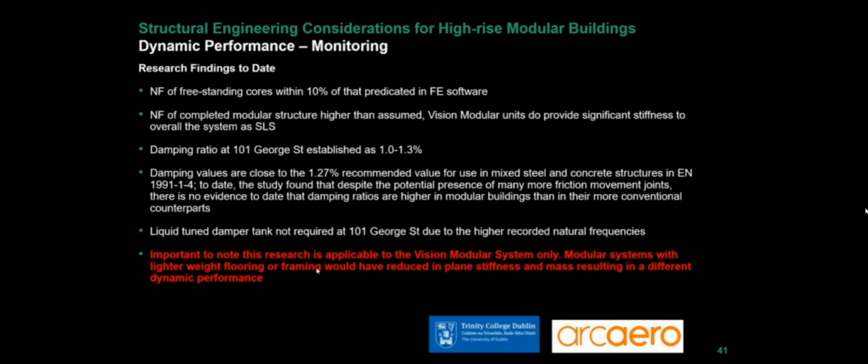So, research findings. Now this is still ongoing and will be ongoing for a few more years, because we need to build up a database of all these buildings and exactly how they perform. But the natural frequency of the freestanding cores, which are the slip-formed freestanding cores, were within 10% of what the FE software predicted. That was assumed to be the case